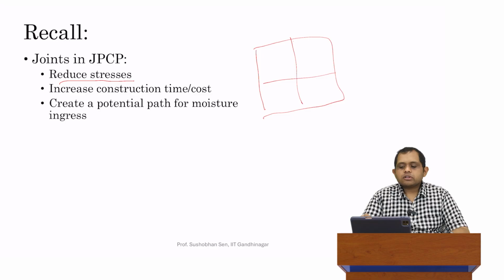However, the problem is, in order to make the slabs as small as possible, we have to physically go in and saw those joints. That process is fairly labor and equipment consuming, it's time consuming, it's expensive. So we cannot saw in very small joint sizes for highway applications. It would start becoming uneconomical at that point. So we try to find something in between, and we'll talk about how we can improve that particular aspect today.